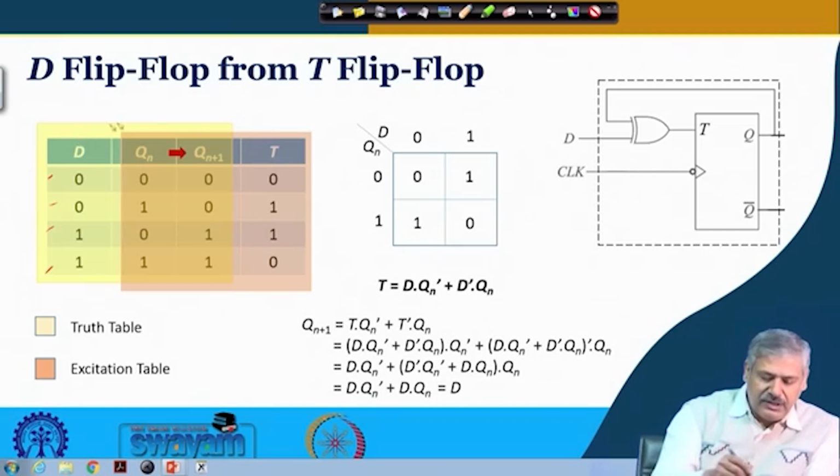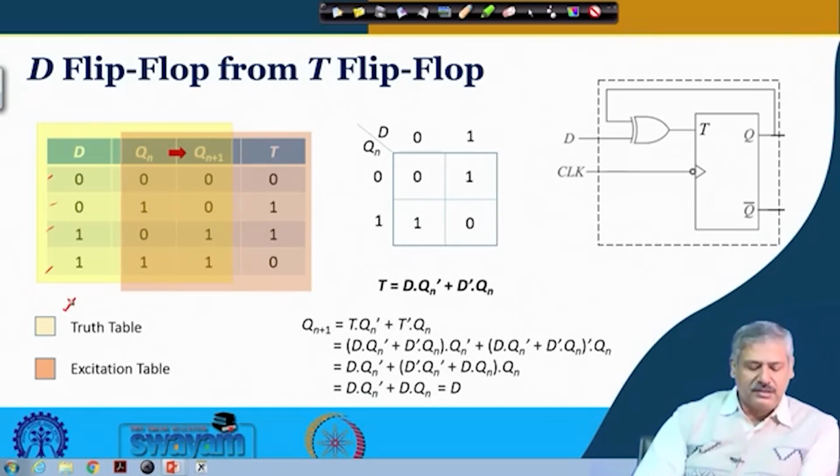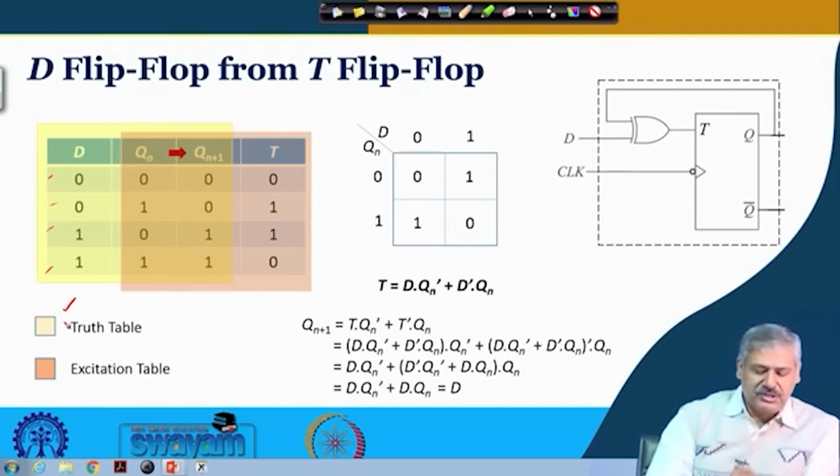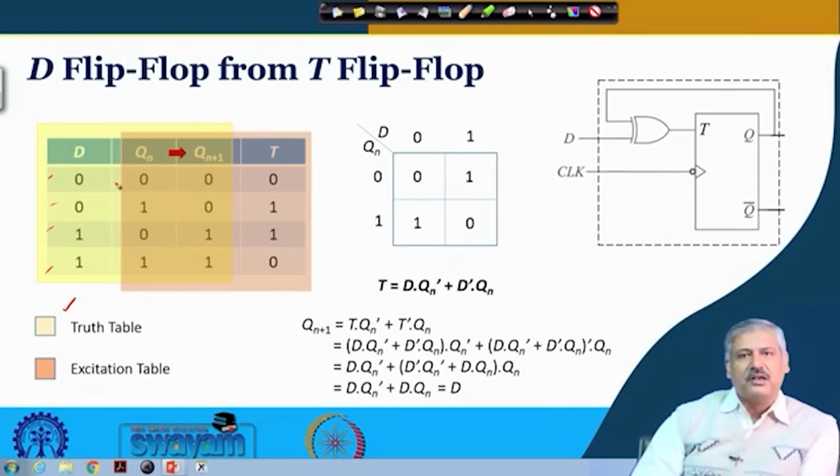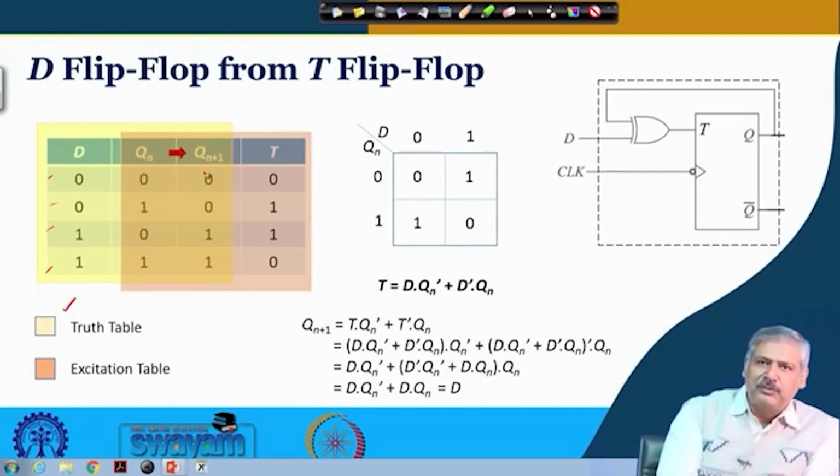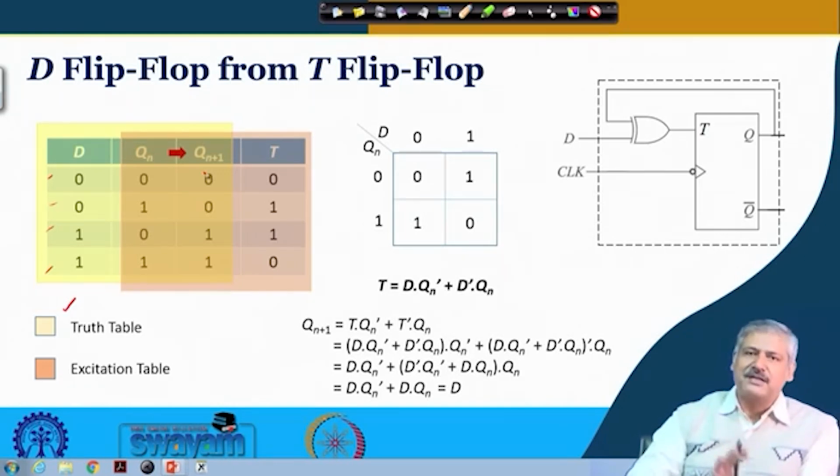The first part of it, the one in this yellowish color, is the D flip flop truth table. The flip flop that we want, the truth table of that would be written. So, that is this generalized method we are talking about. It will apply for any other case. We shall look at another example in the next slide.